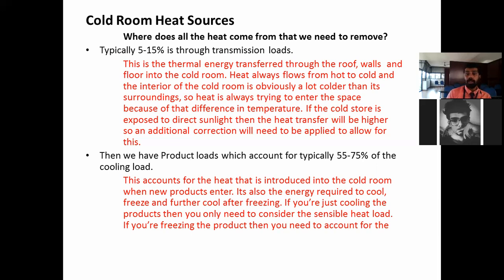So see this, 55 to 75% of the heat is produced from the products that we are going to store. This accounts for the heat that is introduced into the cold room when new products enter. Sometimes products will be taken off again, another product will be coming, the same product will be coming, circulating, right? It's also the energy required to cool, freeze, and further cool after freezing.